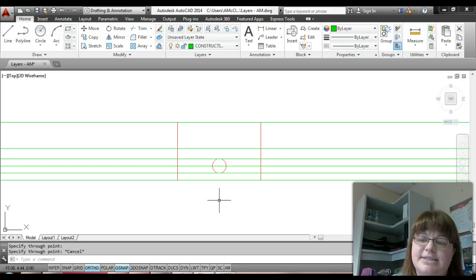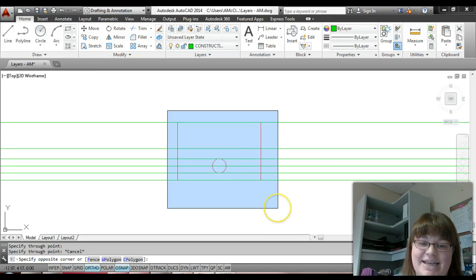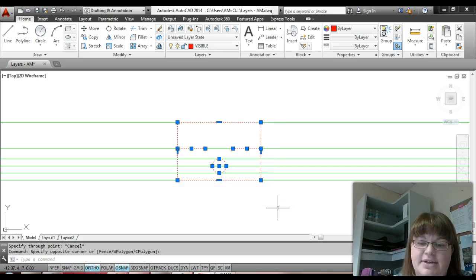So we just drew some construction lines and they go infinite length left to right. Those are horizontal, they go through the points. So the next thing you'll notice is what happened to our red lines that were back here. Well, they're there, you just aren't seeing them exactly. If I draw a box from the upper left to the lower right, you'll see that they're all there. I just selected them, you can see the blue grid boxes.